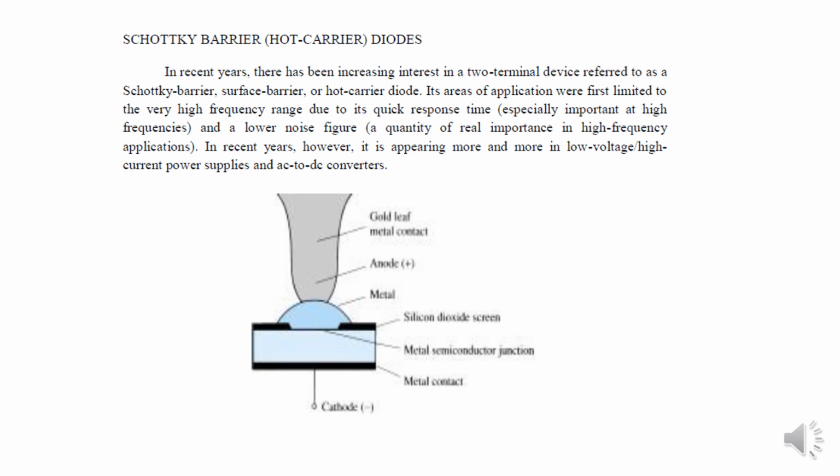The semiconductor is normally an N-type semiconductor, with a lot of different metals such as molybdenum, platinum, chrome and tungsten used. Different construction techniques will result in a different set of characteristics for the device, such as increased frequency range, lower forward bias and so on. The priorities do not permit an examination of each technique here, but the information will usually be provided by the manufacturer.